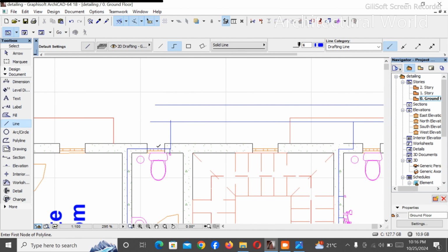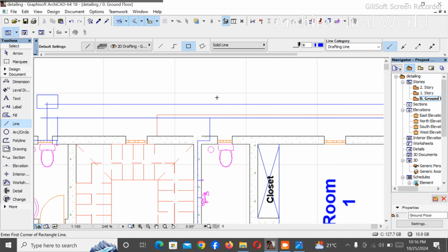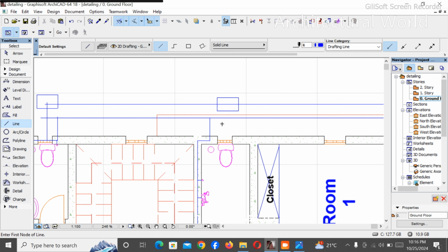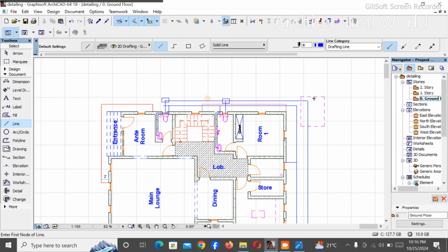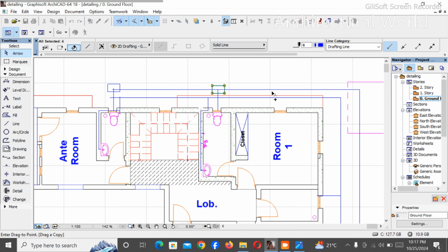So automatically, this is a 4-inch pipe that comes to this part, and a chamber is highly needed here. You can see. Then from this part again, a chamber is also needed, and the 4-inch pipe has to go in. You can see. Then from this section, we need another chamber here.